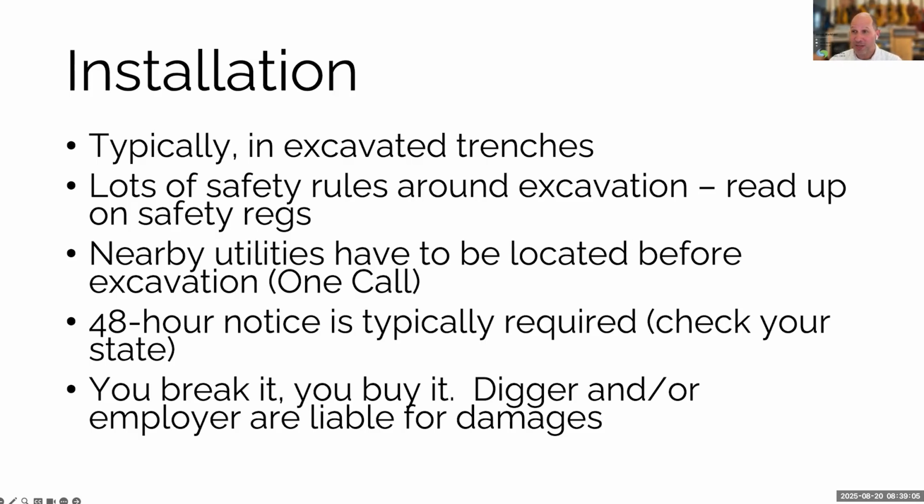Typically, when you are digging, if you run into something, it's a you break it, you buy it kind of situation, right? Here on the mainland, we have One Call. I'm not sure whether an equivalent thing exists in the territories, but the idea is there are a lot of different kinds of utilities that are buried out in the streets. And when you're going to go dig holes, you want to make sure that the other utilities have an opportunity to come out and tell you where their stuff is so that you don't accidentally tear up a fiber optic cable or hit a gas line, or, as in, put a telephone pole through your sewer or something like that.